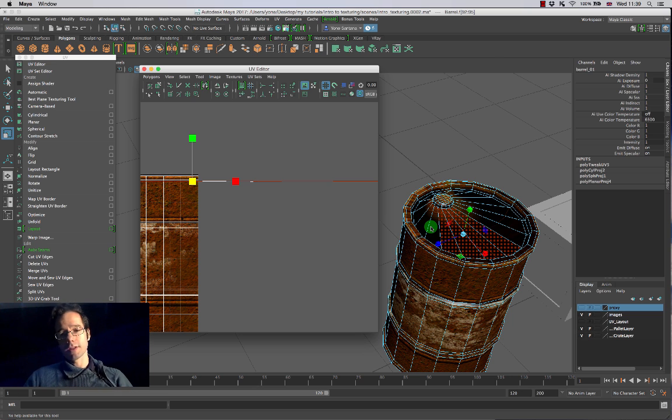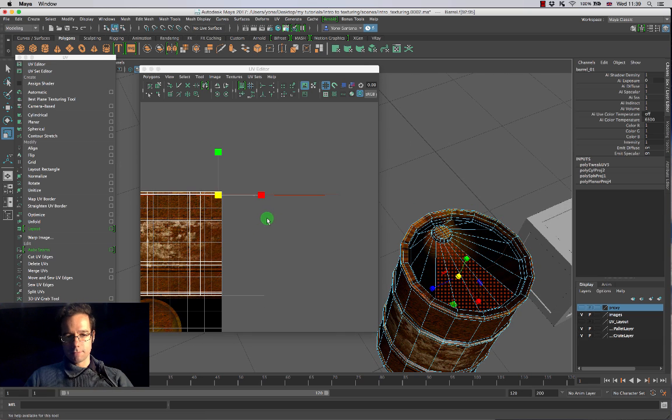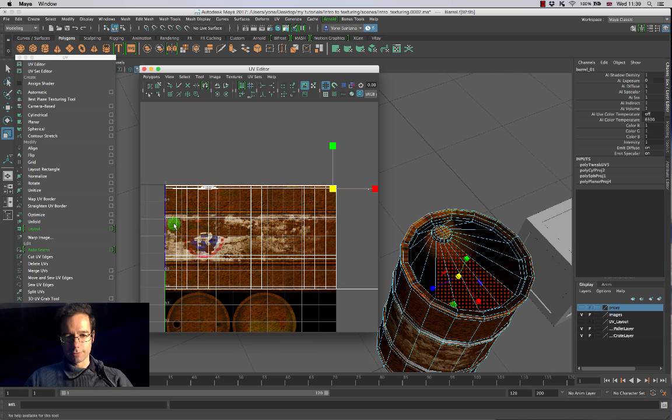However, it's very handy that we can actually make multiple projections. What I mean by that is, I've currently made a temporary cylindrical projection at the top of this object. I can do projections based on specific selections in the viewport. Here's another handy selection tool, this little brush selection tool, which if I come over here into Maya, you'll see that I get this little 3D brush. You can change the size of it by pressing B and dragging the size of the brush, just like that.